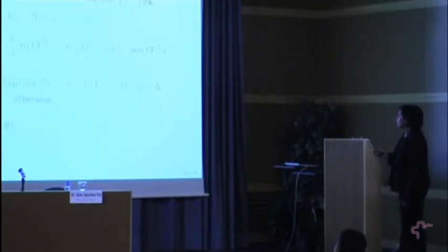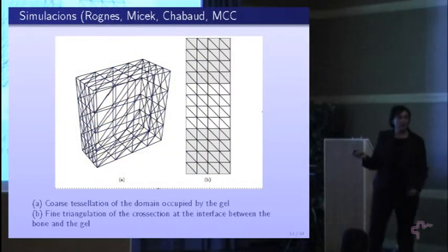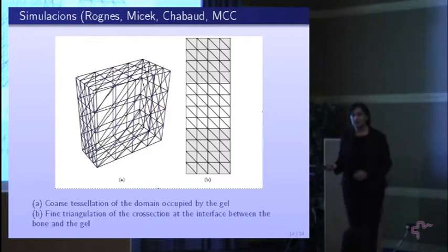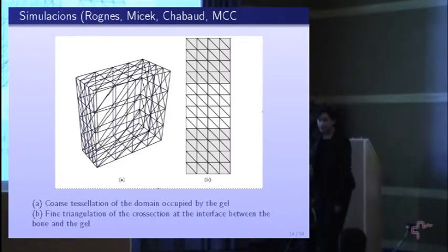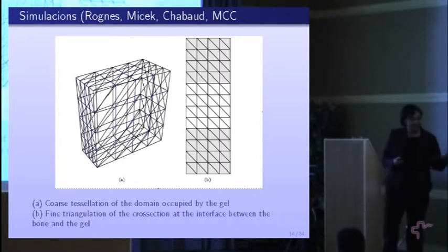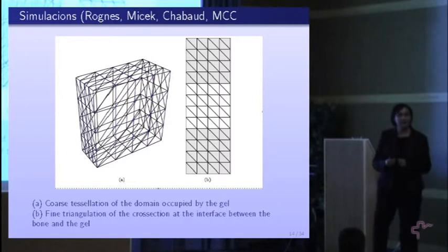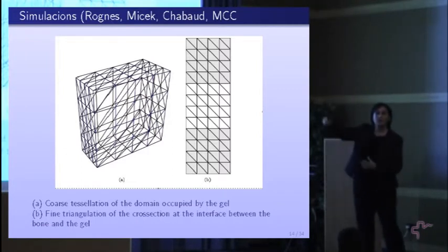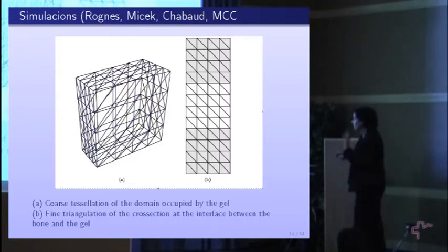Okay, so now, the first question that we ask is, when we have this energy, does this energy have a minimizer? Dr. Regura talked about that, and yes, under the right conditions, we can minimize that energy. In other words, there is a minimizer, and we need conditions like, for example, the elastic energy gets very, very big if we stretch a lot, and also gets very, very big if we try to compress, say, a finite volume of polymer down to 0. And so that's two basic properties.